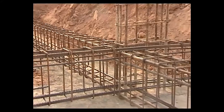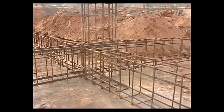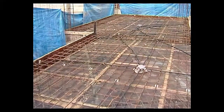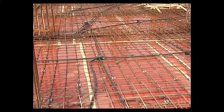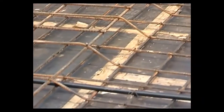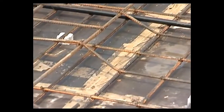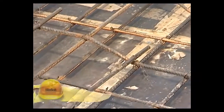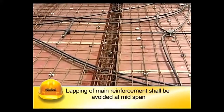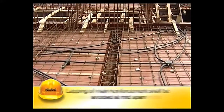The same importance for the number, position and spacing of reinforcement bars in slabs shall be given. The location of bending up the bars and proper tying as well as provision of cover blocks and chairs for top rods shall be inspected by a professional engineer before concreting. Lapping of main reinforcement in slabs and beams shall be avoided at midspan.